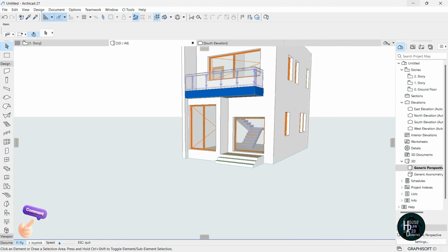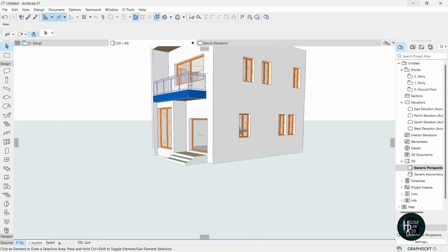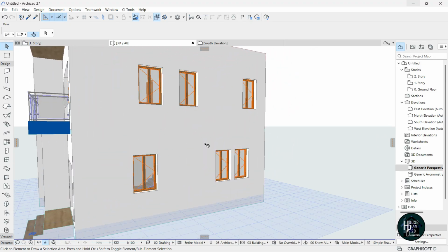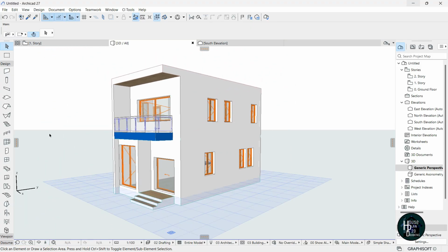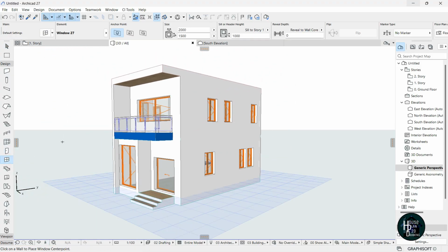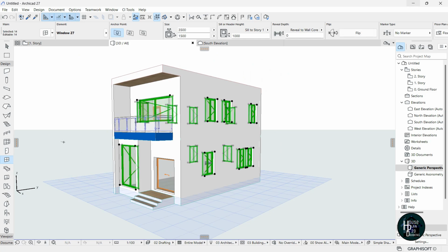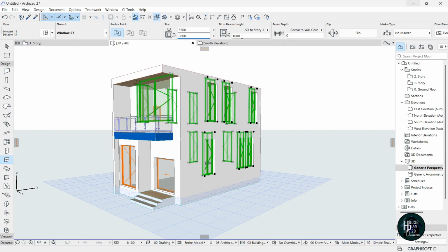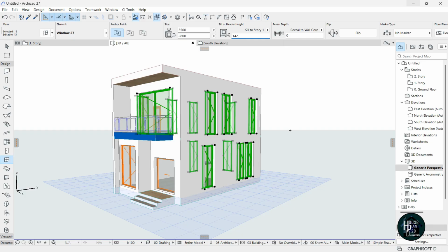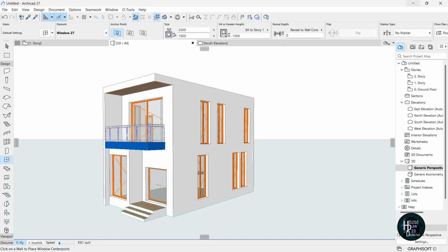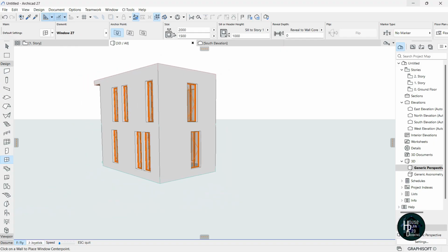Now let's do it for the rest of the windows and the doors. Okay, so what you want to do is just click this window here, or if you don't want to do that, you can decide to just click on the window 2 here, press Ctrl E on your keyboard. Okay, now untick this one that I just edited. All right, now change this to be 28. Click enter. Now come back and edit this one to be 142. Click enter. Okay, press escape on your keyboard, and that's gonna make the perfect adjustment for this particular drawing.